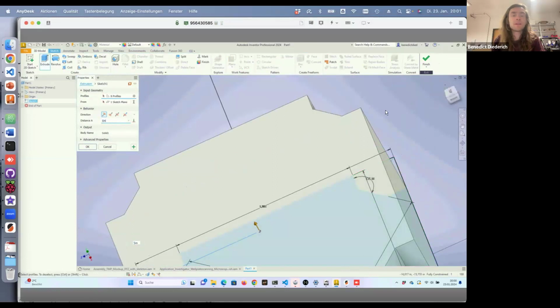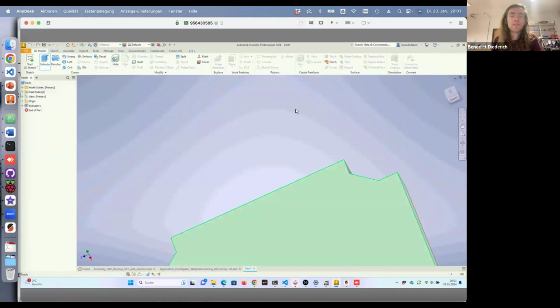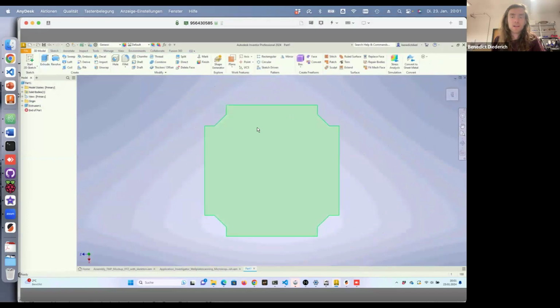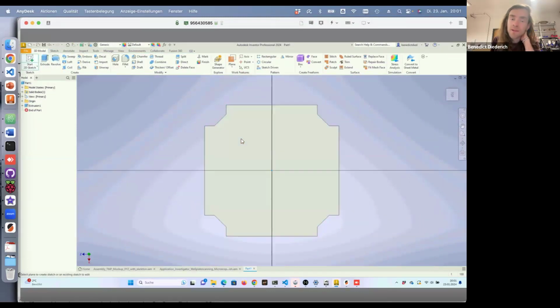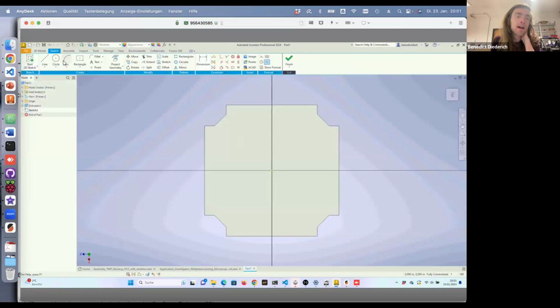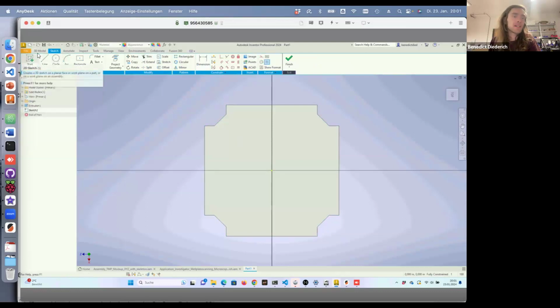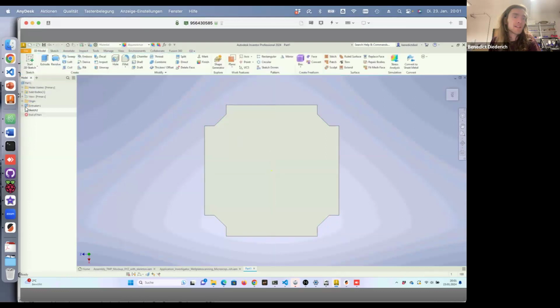We just say it's 5 millimeters. And then we already have the insert part, which goes into the cube, like that here. And then if we want to add a lens, which is snapped into this thing, we can be smart and say, okay, we really want to snap that in and make it like that.